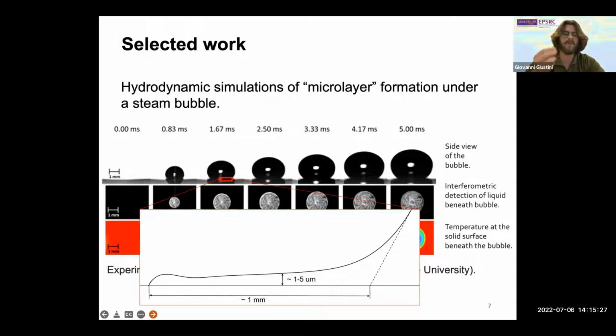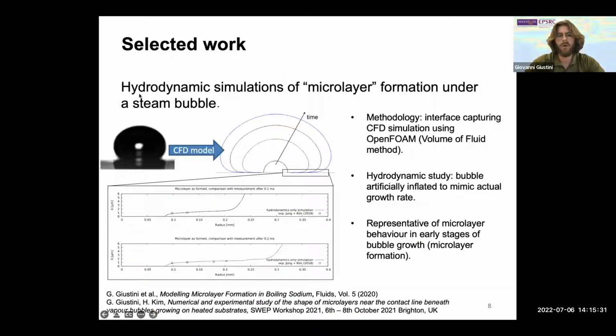Right, so can we study this kind of physics with CFD? Well, the answer seems to be yes. With interface capturing simulation, we can develop detailed, high-fidelity models of the hydrodynamics of the growth of a single bubble at the surface. And from these models, we can study the behavior of the liquid film beneath the bubble.